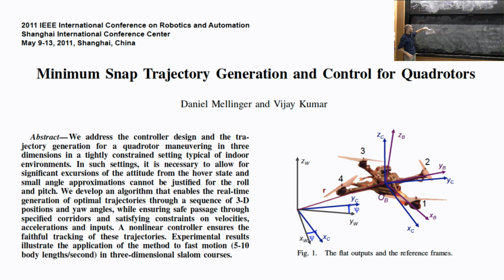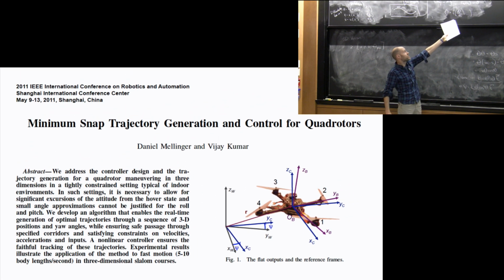So then, given that, you specify those 3 variables, you get a second derivative of, in order to compute these variables, you need to get positions up to the 4th derivative, which is jerk. And in order to make nice trajectories in all those variables, you'd like to have smooth jerk, which you can achieve by doing minimum snap.